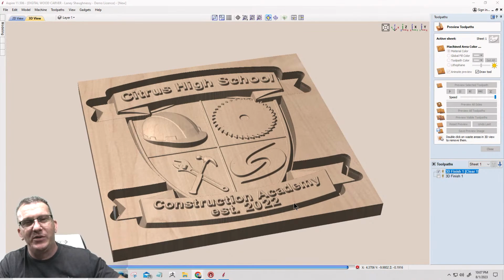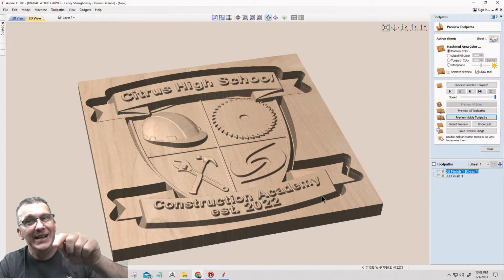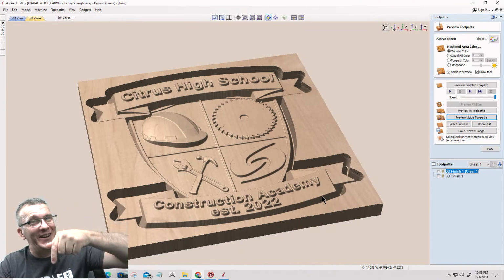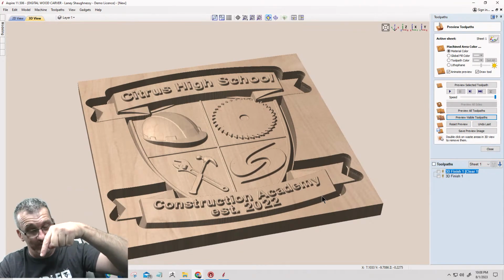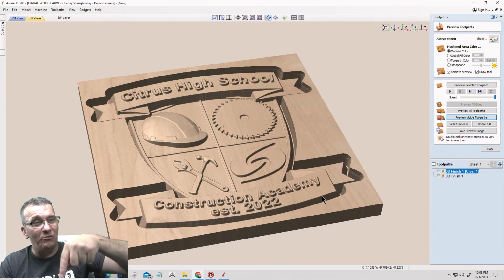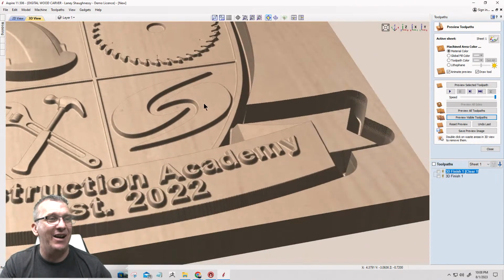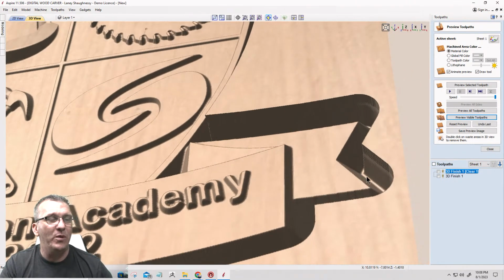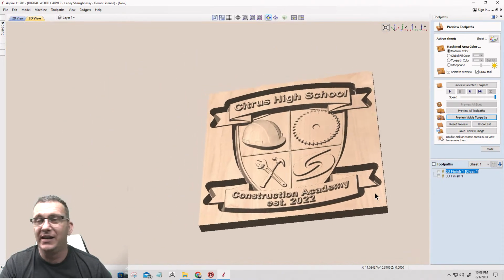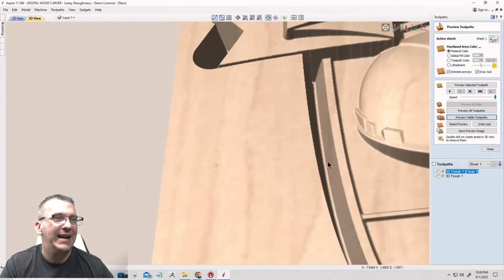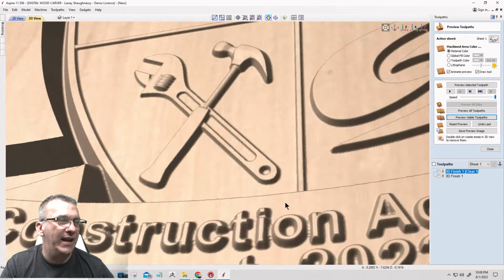But this particular carve absolutely requires a rough cut to hog away this waste material, because the finish cut does not make passes, ladies and gentlemen. It does not take passes down to the final cut. It plunges to the depth of the full model, and it rides that model to create the carving. So imagine if I did not rough cut this, my ball nose bit would be plunging through this and would be burning itself on the edges and everything, because it doesn't make passes, right?